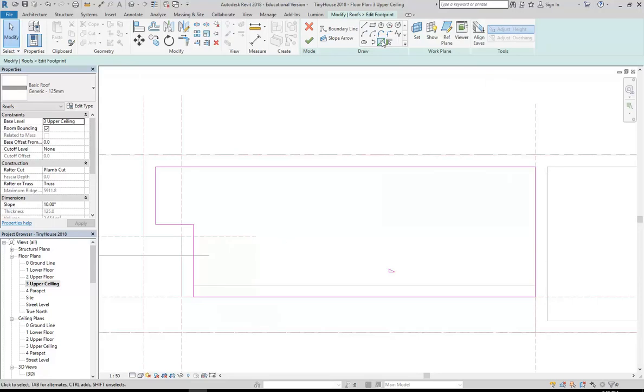Pick lines, so then you should be able to pick any side. But then did you use pick walls for the first one? Isn't that what we do? No, pick lines and pick walls are different tools. That's the whole point. So pick walls for the first one that has the slope, and then pick lines for all the others.